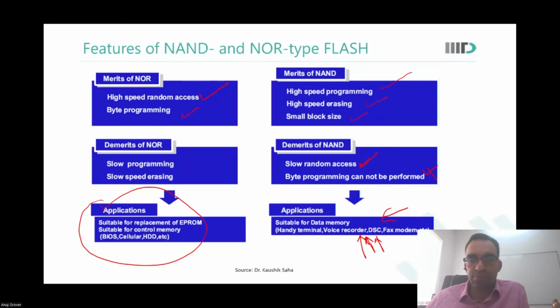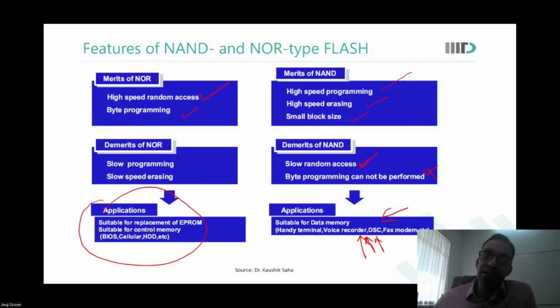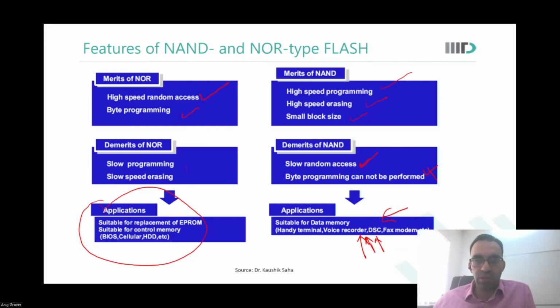Okay, sir. One more confusion then, sir. When we see the timing diagram, we were initially sending the column address, and then we are sending the row address. So would it create any race condition during the burst mode access? So again, you would want to do it according to what is the requirement there. Here when you select one particular row, you are actually selecting the entire page, reading the entire page anyways. So you may not need any further thing for burst mode access inside the memory. When you brought it to the plane of your SRAM, then you can decide how fast or how slow to read there. Okay, okay, so first bring it to the SRAM plane, and then do the burst mode. Okay, got it.